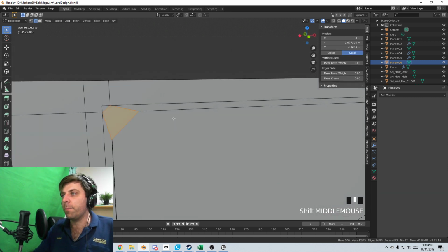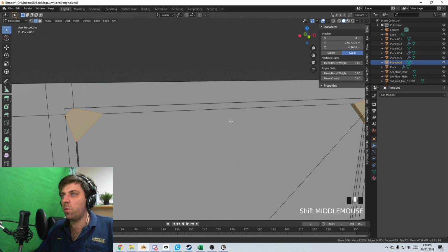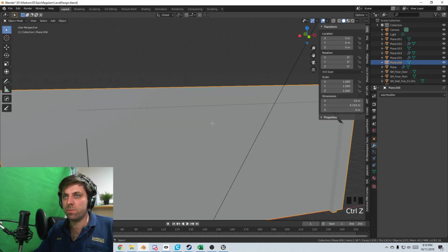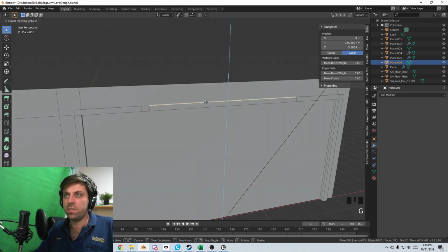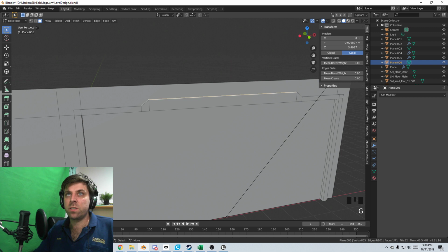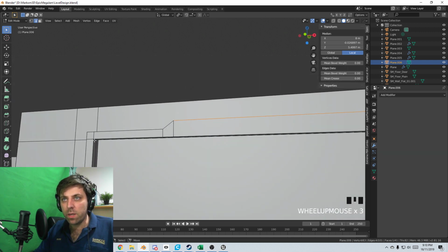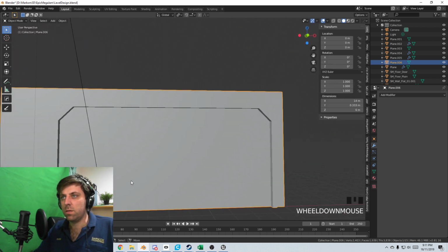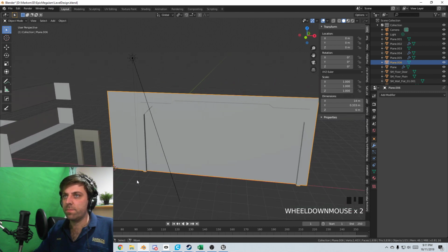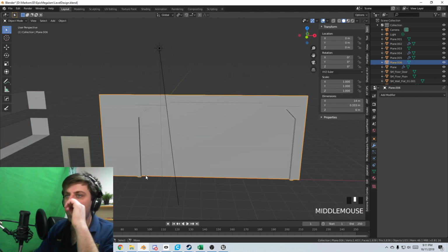Okay, so from here, let's do what I did before, which I can't now, Control Z. Let's undo that. Let's put our bevels in. Select these two, Control B. Let's select this face, G Z, might as well keep with the architecture. And now we can come in and select here, Control B. Lovely. Cool beans.